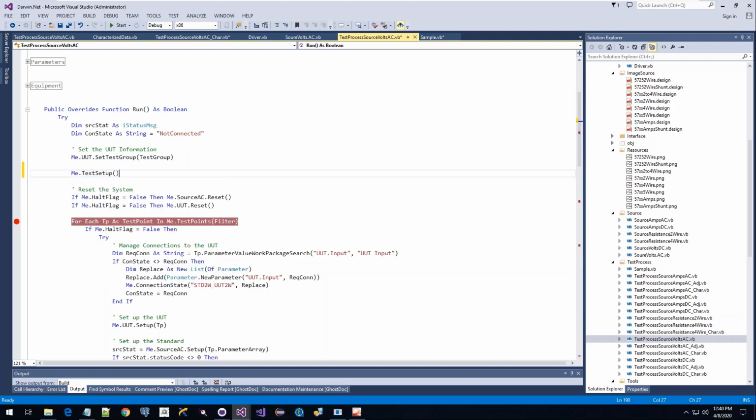As far as what we're going to run, it allows us to set the number of measurements we want to take, and it'll let us set what the UUT address is. Then we're going to set up our source. So you see we're talking to the 5720 or 5700 with just source volts AC, go reset yourself. And then here, same thing with the unit under test, just go reset yourself.